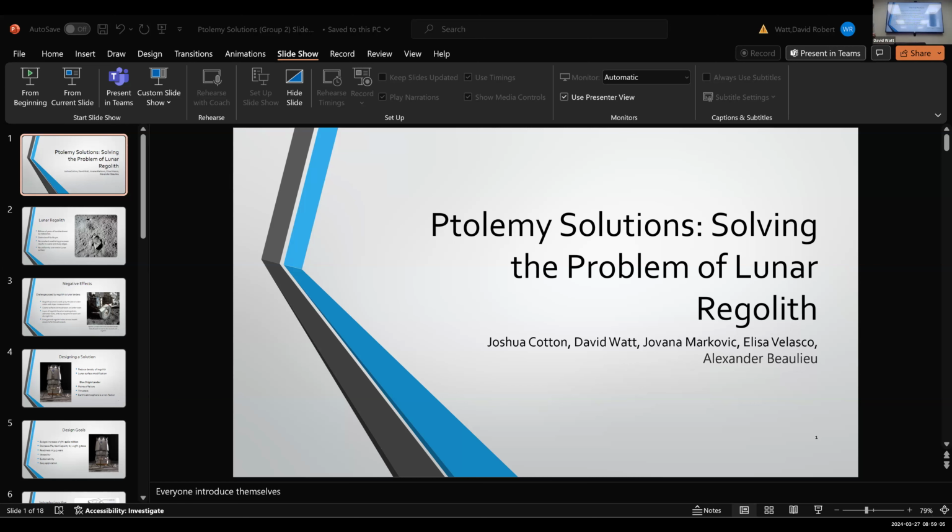Okay, so the thermal analysis, the main issue here is radiation from the sun. The motor internally that turns the wheel lock produces a very insignificant amount of heat. So our main issue is, how much, based on radiation, is the outer part of the capsule going to heat up, and then based on that temperature, how much conduction is going to occur, and how much heat transfer is going to go into the capsule.